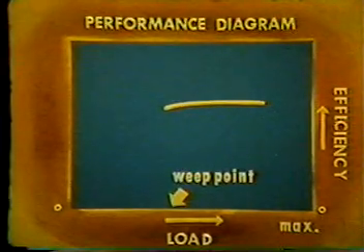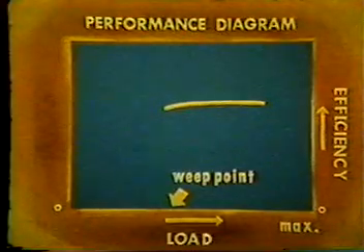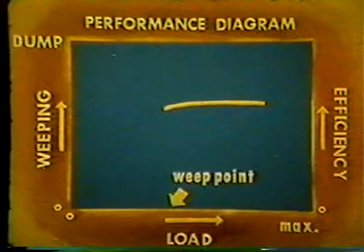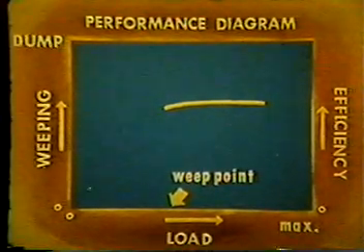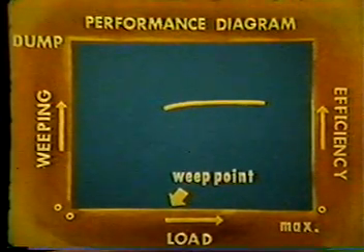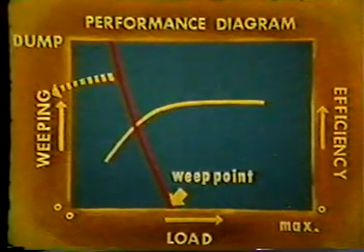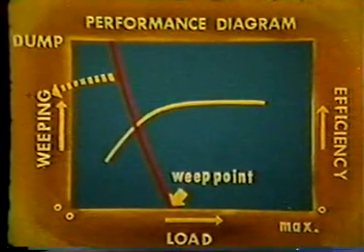The weep point is a function of the tray geometry and the physical properties of the system. When the vapor rate is reduced further, the sieve tray will begin to weep more and lower the separation efficiency. Experiments have shown, however, that an appreciable amount of weeping, as much as 20% of the liquid, will not necessarily be harmful to the separation efficiency.